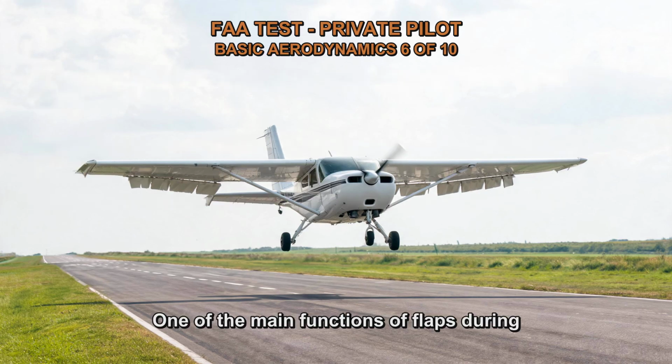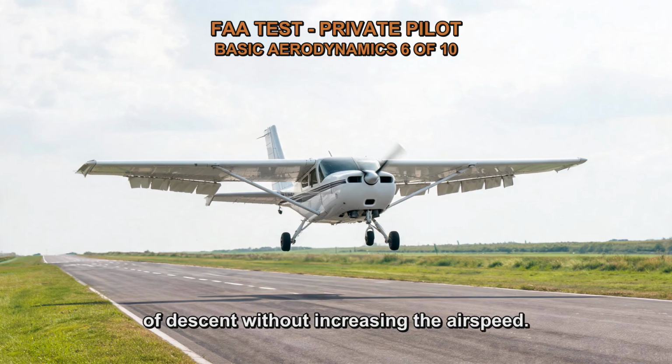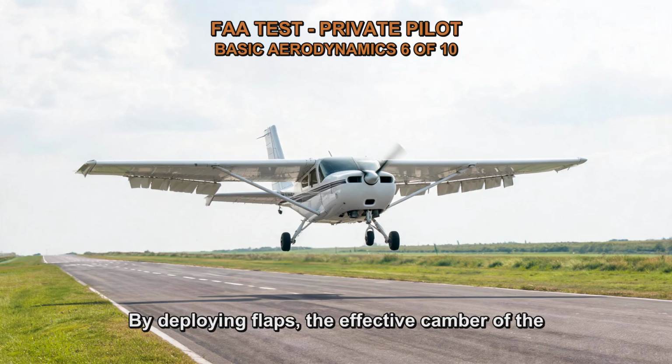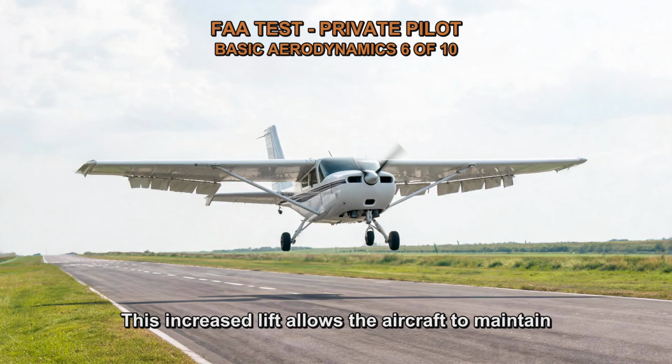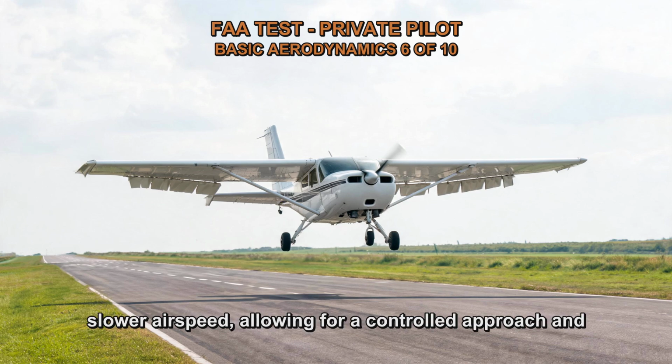One of the main functions of flaps during approach and landing is to increase the angle of descent without increasing the airspeed. By deploying flaps, the effective camber of the wing is increased, which generates more lift at a given airspeed. This increased lift allows the aircraft to maintain a steeper descent path while maintaining a relatively slower airspeed, allowing for a controlled approach and landing.